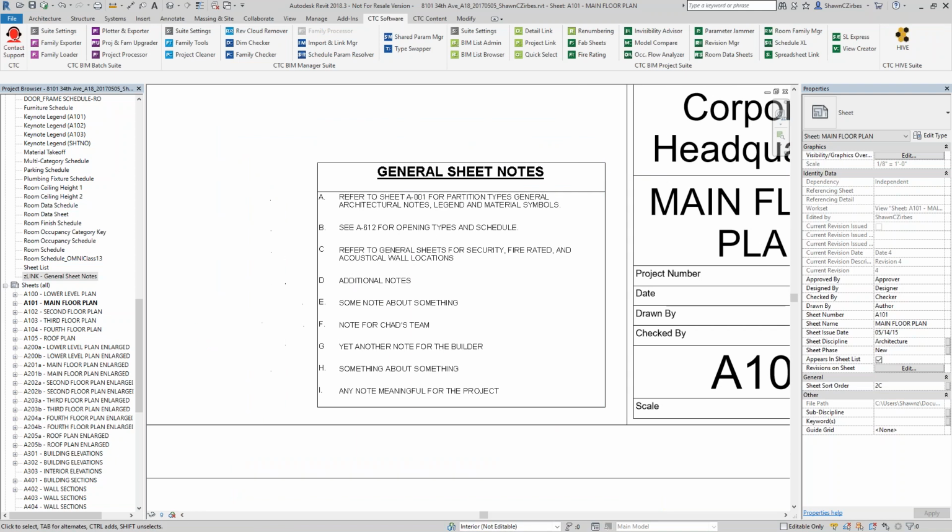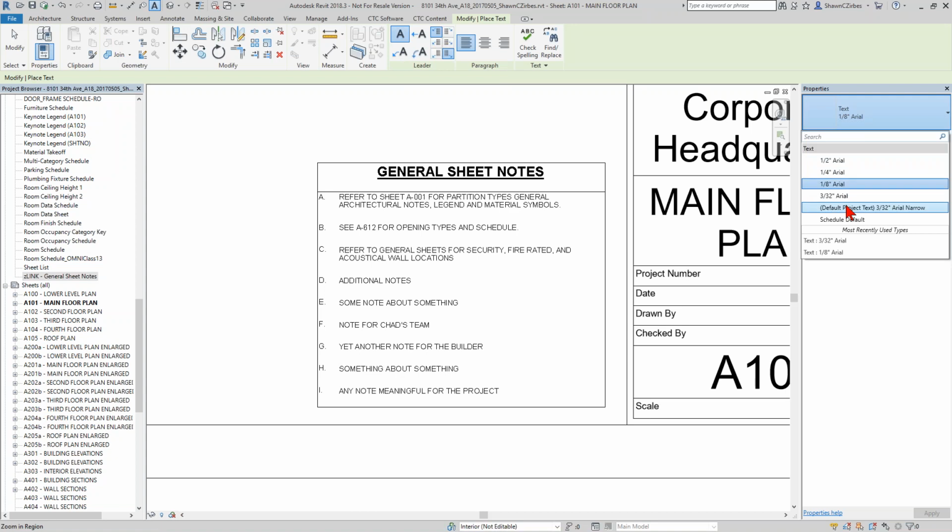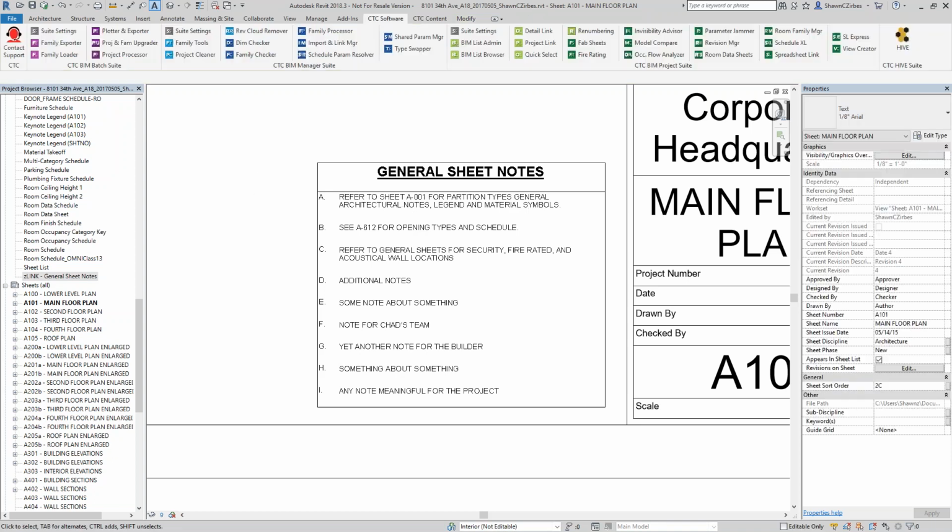any new text types. In fact, if I type in text here, normal Revit text command, I'll see that I have just a few text types brought in, and that was really it. Whatever they are. The actual text types coming from Excel don't get brought into this environment when I use the schedule option. And I'll show an example of that in a moment here with that other schedule where the header is actually using that Book Antica type font.